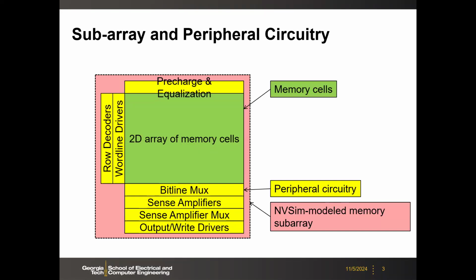And then you have the memory cells, either SRAM, DRAM, or emerging memories, the 1T1R or the cross points. Here, the array is made of word lines and bit lines, and each cross point will be the memory cell. Maybe you have the transistor there as a selection element plus the memory cell. Around the array, we will have several modules for the peripheral circuitry.